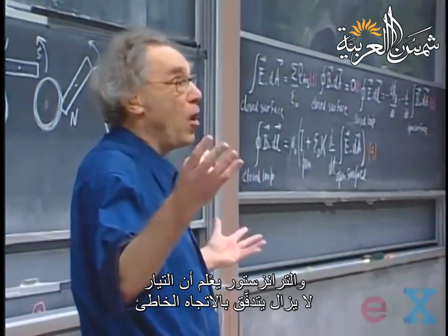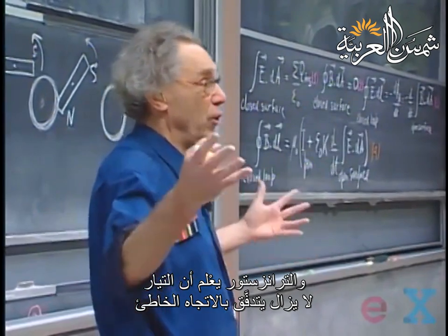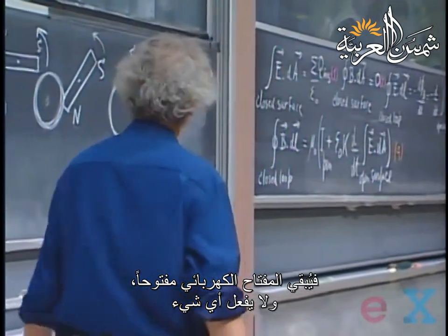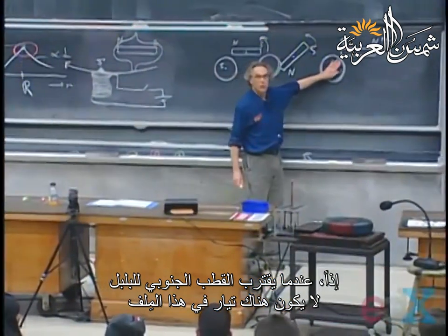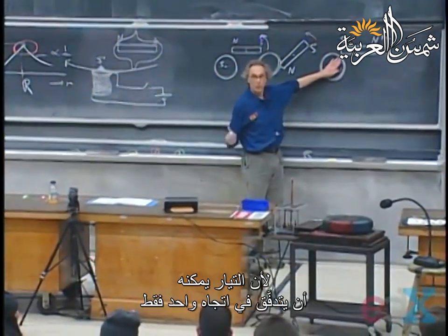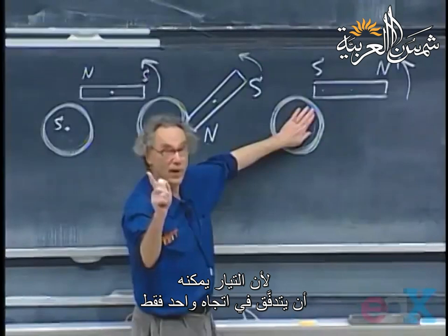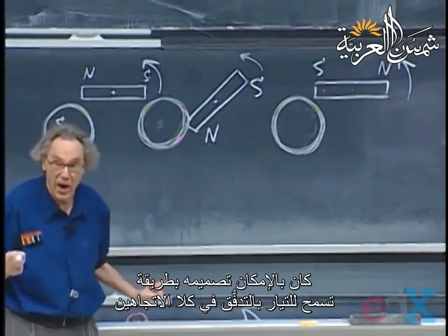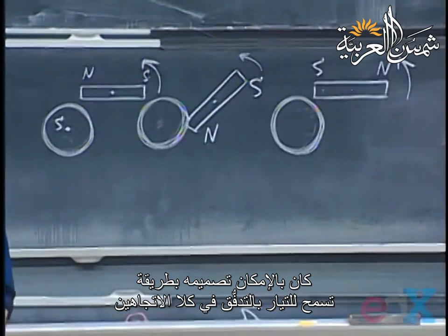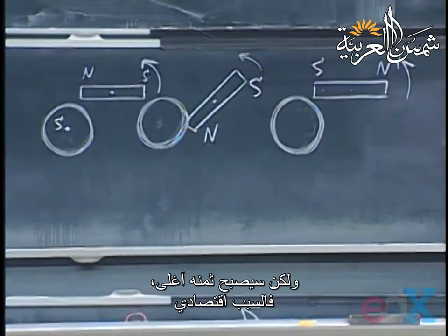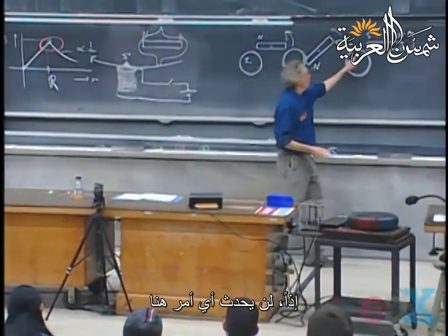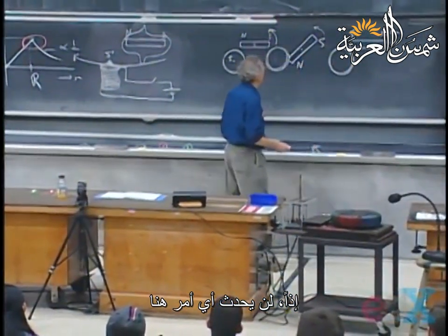And so the transistor knows that indeed the current is still in the wrong direction. It keeps the switch open. It does nothing. So as the south pole approaches, no current through this coil. Because remember, the current can only go in one direction. It can only make this a south pole. It could have been designed in such a way that the current could go in both directions. That would have made it more expensive. It's just a matter of economy. So, nothing will happen here.